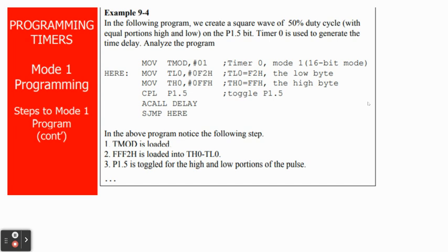But the question does not mention the mode that we will be using. So let's just say we will be using mode 1, which is 16-bit mode. So it will be timer 0 mode 1.